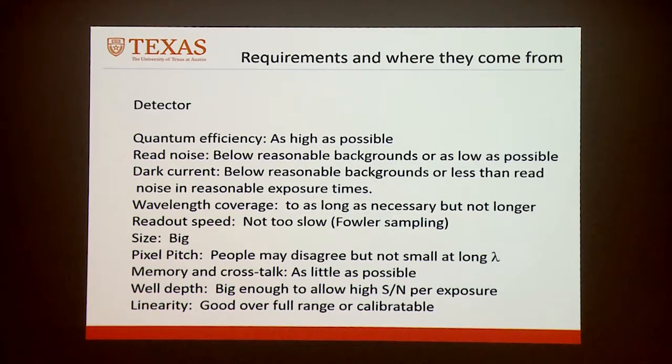You want the readout speed of your detector system to be reasonably fast. And the reason is that because the detector noise is not perfect, we tend to read these detectors out many times in order to lower the amount of noise by averaging over the reads. And if the detector moves slowly, you actually lose time doing the readouts. Also, at the long wavelengths, the wells fill up pretty quickly because of all that background. And so you can't expose for very long. And if it takes a long time to read out the detector, you waste a lot of time that way. So they need to be able to move.